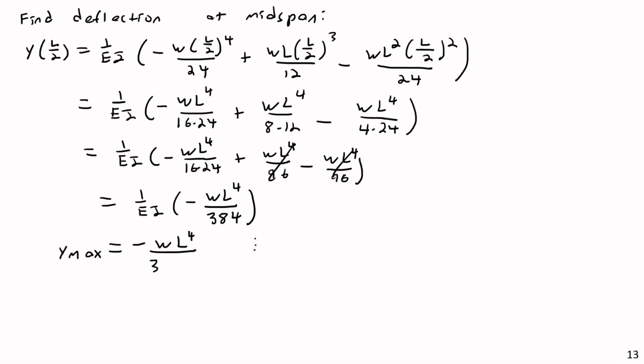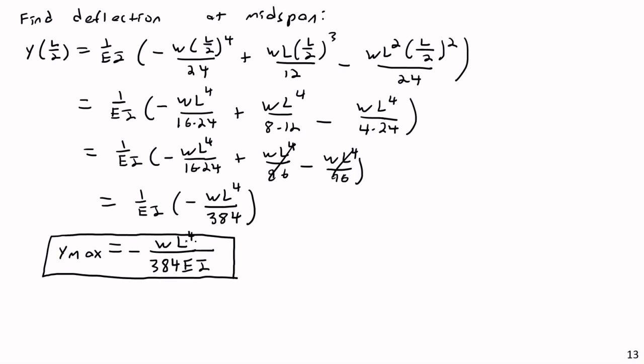Now, the only question then is where the negative comes from. In that equation from the steel manual, they were defining downward deflection as positive. The notation I've been using describes downward deflection as negative. So that's the only source of the disconnect there. But we have seen where this equation comes from, and we have derived it using the force method, and also plenty of deflection via integration.